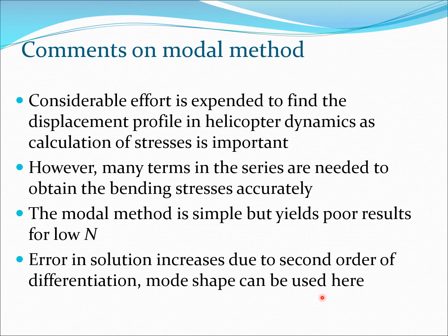So mode shapes differentiate very well and therefore the results will be quite good. Now in general, one of the reasons a lot of effort is expended in rotor dynamics to calculate the displacement profile very correctly is that the calculation of stresses is very important. And the calculation of stresses being very important, the displacement calculation is extremely important, because very often, like in the modal method, the stresses are coming by differentiating the displacement, and that also differentiating the displacement twice.